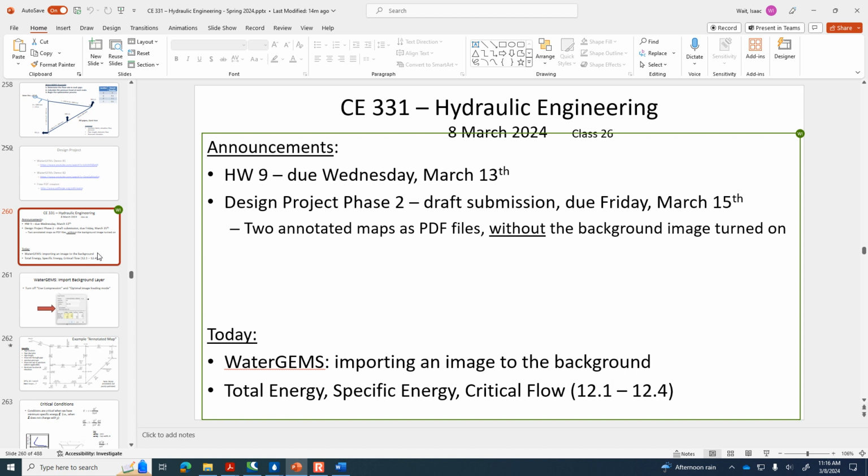You can just go with your flow rates as you understand them now, and then if revisions need to be made later on, it's very easy for the final submission to modify your pipe sizes once you've got updated flow rates. So just proceed with the flow demands that you've already calculated, unless you get your comments from me early enough that you can integrate them and adjusted flow rates into your network sizing.